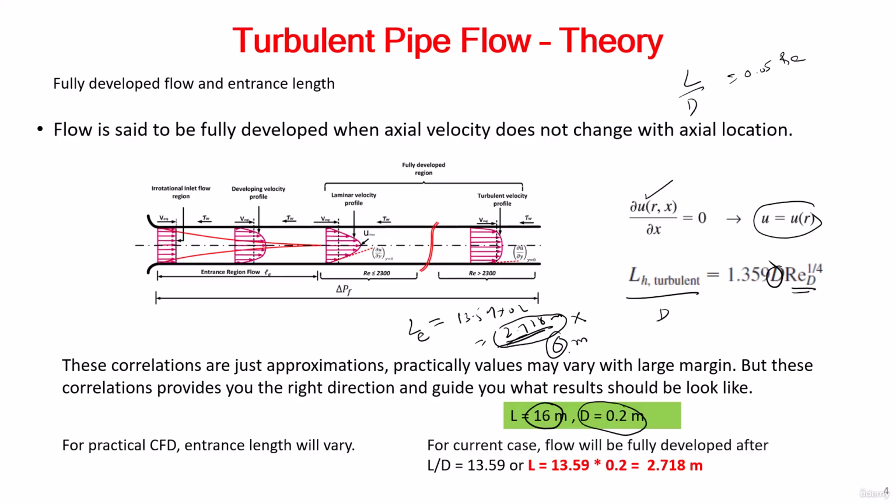The solution, which I will show in the coming sections, is that you can reduce the pipe length by applying the same velocity profile through a UDF, or through an expression, or a profile file. The profile file can only tackle simple profiles like these ones; they are handled very well. Expressions can handle them with more options and more functionality. And UDF is the ultimate thing, where you write C code and couple it with Fluent.